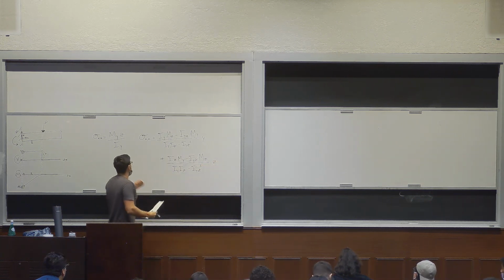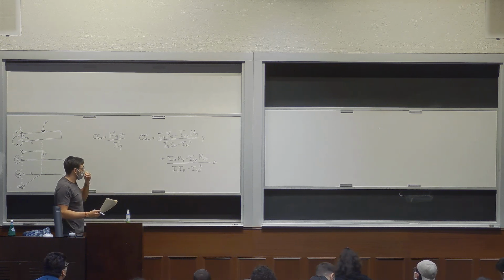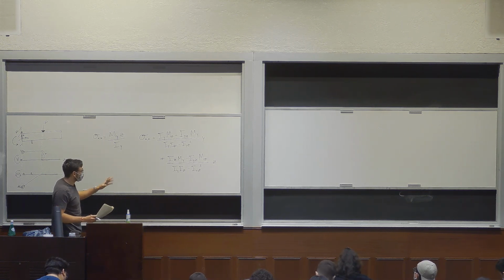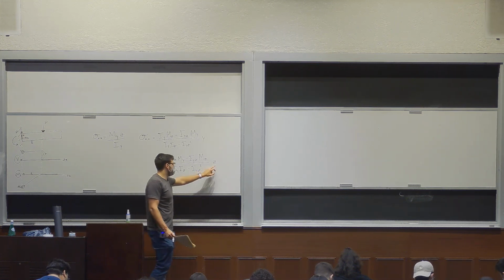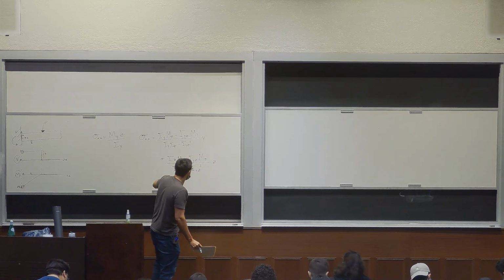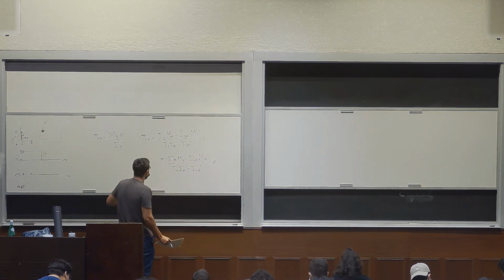Okay, so this is the full equation for any given problem that you got, right? If you have bidirectional bending, and of course you would plug in the position z, y for whatever point you're interested in on the cross section, and find what the normal stress is there.